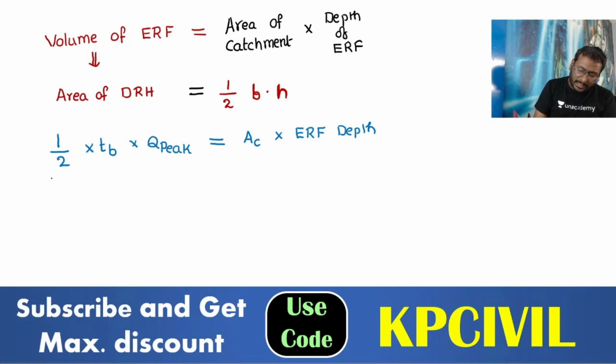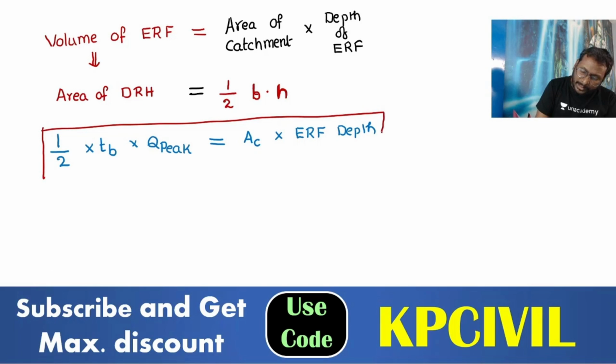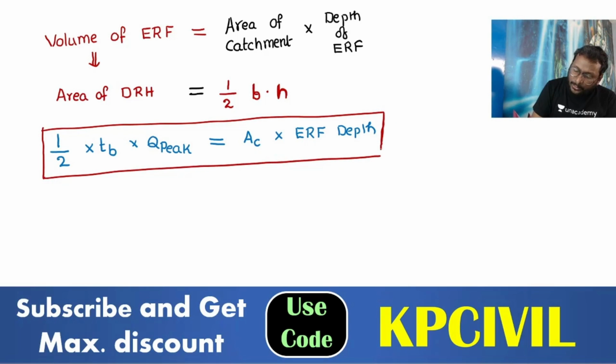For any triangular direct runoff hydrograph, you can use this formula. If your hydrograph is a unit hydrograph, in place of effective rainfall it is the direct runoff, and you take 1 centimeter depth, that is 10 power minus 2 meter.